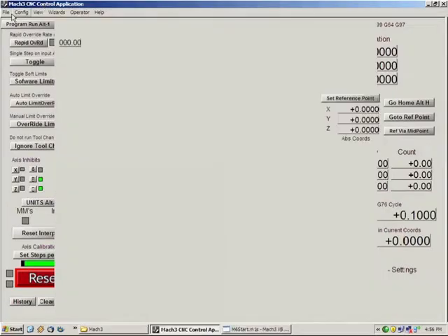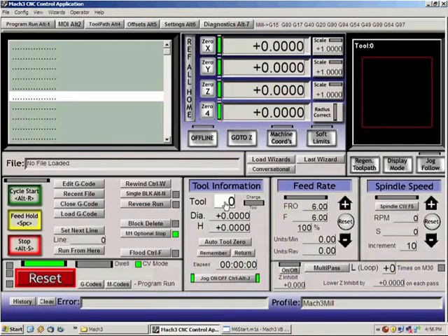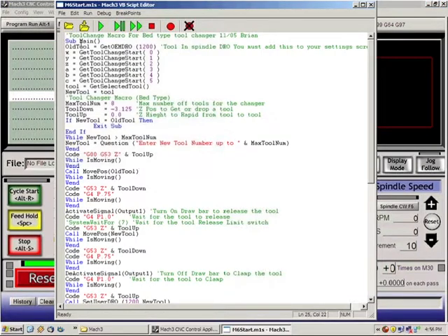If we want, we can actually scroll through it step by step. The only thing I'm going to do before we go through and run our tool changes is give this a tool 6. That way we can see a little bit of what it's going to do. And remember that we have a 4 in this one, which I'll show you how you can check. We do a mouse over and we can check the values that are coming in. So we can just go through line by line. We can see that when you move to X, Y, 0, and Z, it's because I'm in that position.